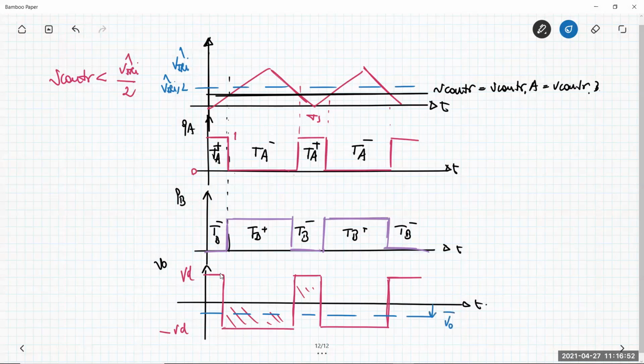But basically, the waveform is, say, the same as before. It is a bipolar rectangular voltage, having two levels, positive VD and negative VD, that switches with the duty cycle derived by the unitary switching function, as said before. The only thing is that this contribution here is narrow with respect to the previous one. The switching frequency of the output voltage is again the switching frequency Ts, and so we have the same behavior as before.